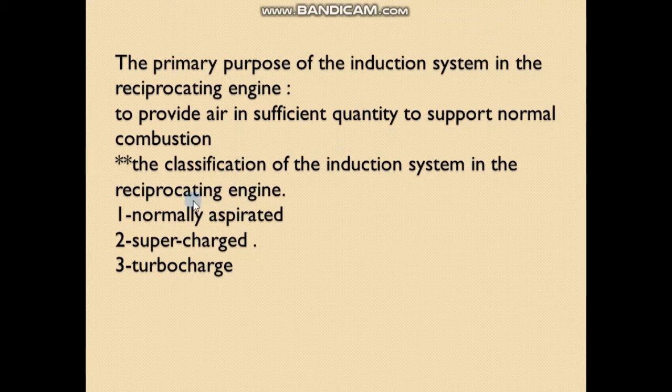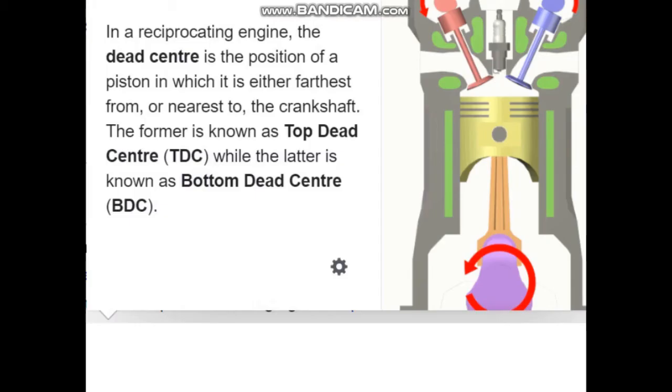In the normally aspirated system, air for combustion, or an air-fuel mixture, is drawn into the engine's cylinders by atmospheric pressure acting against the partial vacuum that occurs as the piston travels downward toward bottom dead center during the air intake stroke.